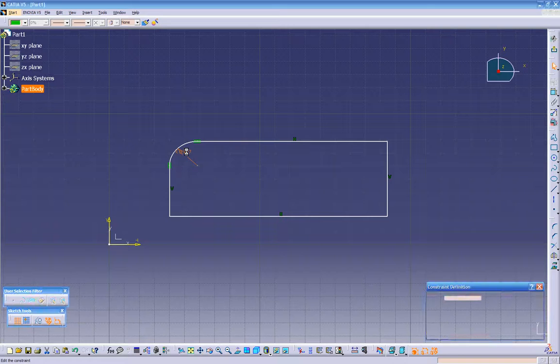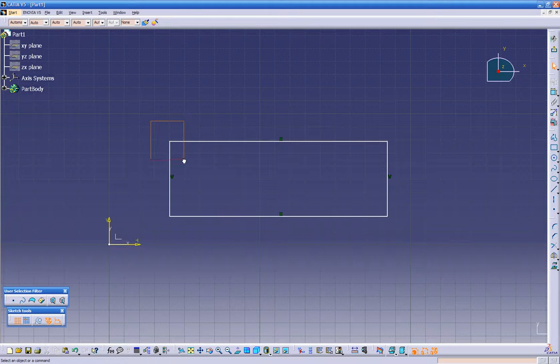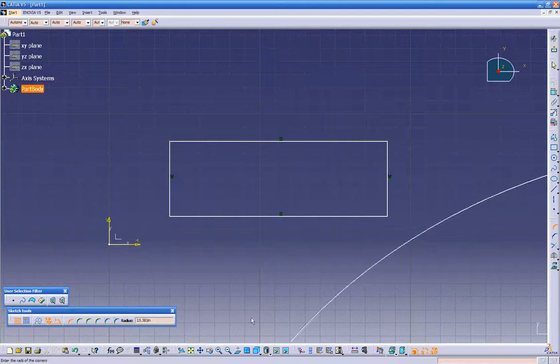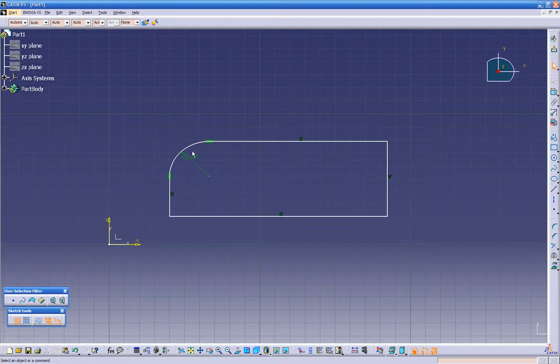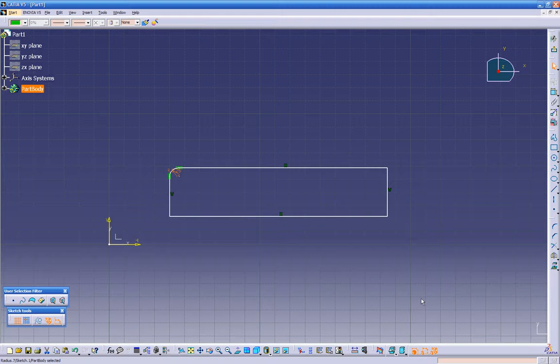And we can give it a dimension 0.250, or Control Z, get out of here. We can just highlight it, corner radius, click the tab key, click on the radius, click 250, and we got our corner radius. Okay, so now if we get out of this sketcher,